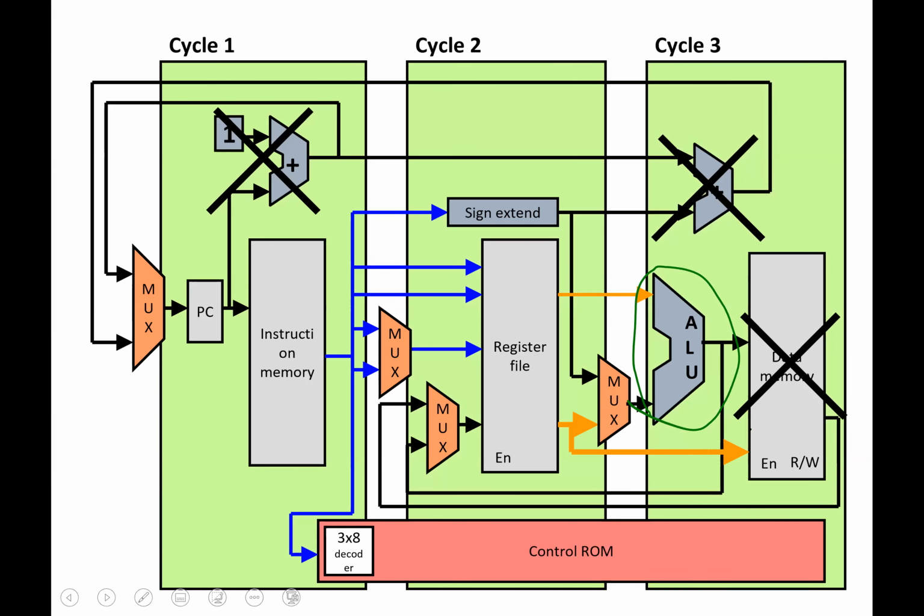For some instructions we're going to take more than 3 cycles, but this is what we're always going to start off with. Then we'll take another cycle or 2 to write results back, but we'll look at the details of that. This is the basic idea: we're taking something that used to take 1 clock cycle, and we're breaking it up into subtasks.